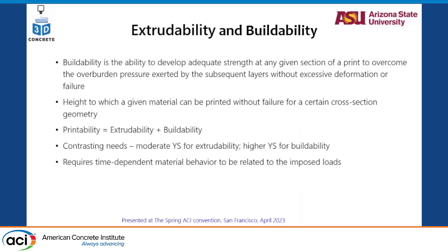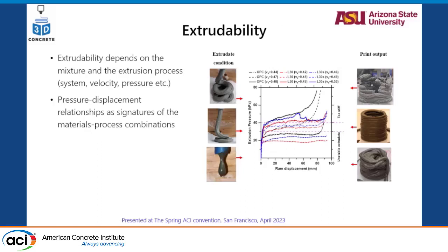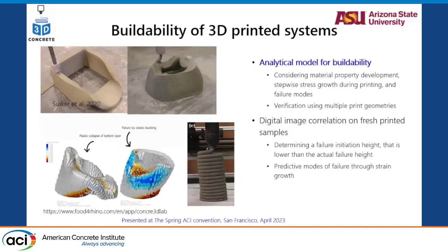When we went through different literature, there were different works about quantifying buildability theoretically with yield stress, rheological parameters, and some mechanical parameters on the green strength. What we saw in literature were cement mortars that have been tested for extrusion. What defines an extrudable mix? Is it just the ability of it to come out, or its ability to come out as a particular shape that you require? Some mixes could be extrudable, but once you place them, they will not retain their shape. So we needed something that retained shape.